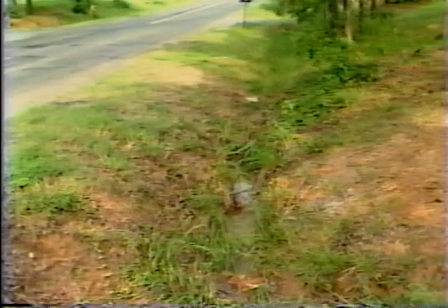Ponding of water in ditches must be corrected. Ponded water can seep into the shoulder and base material underneath the road. This weakens the road structure, and traffic will cause the pavement to break up. Water standing along the entire length of a ditch should also be corrected. It is important that one end of the ditch be higher than the other.